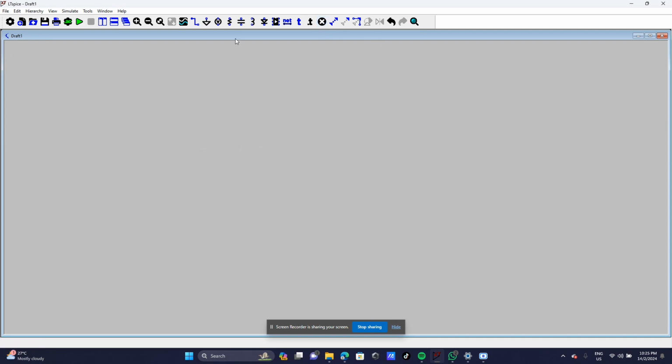So first, of course, we need the voltage source. We just put a voltage source here, and then we need a resistor. We put the resistor here, but we want it horizontal, so we just rotate it, put it over here, and then find the inductance, which is this one. Put it parallel to the voltage source, like that. And then every circuit needs to have its ground, which is the voltage equal to 0. So we just put it down here, and then we connect all of it. Simple as that.